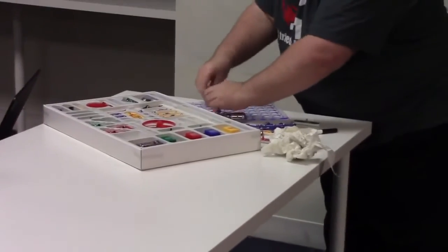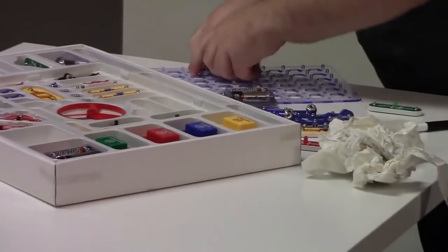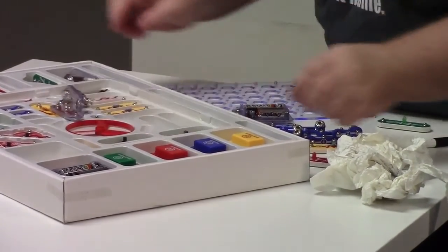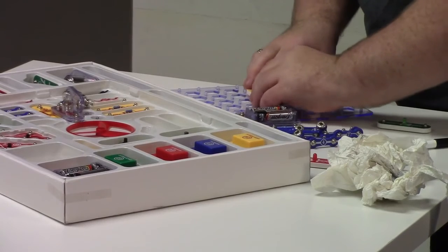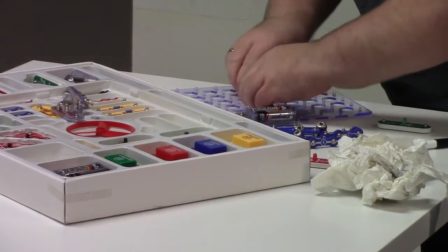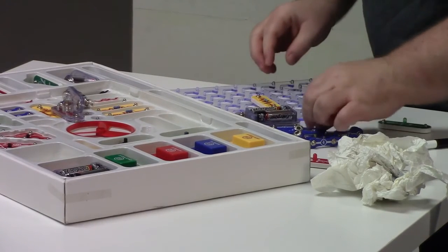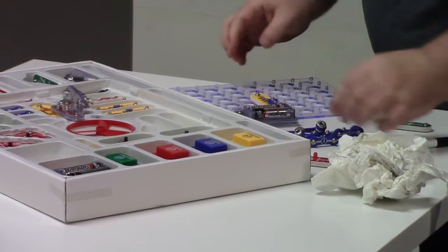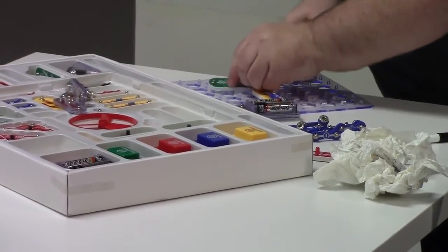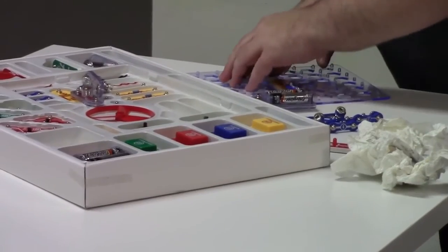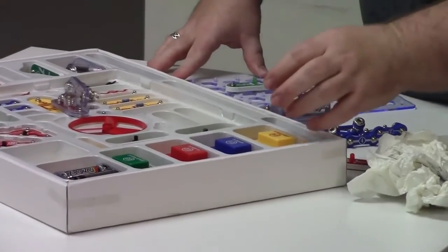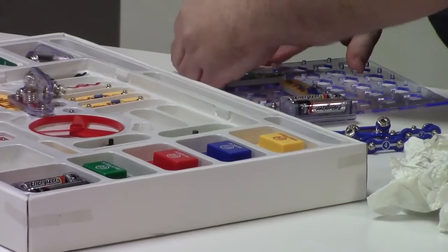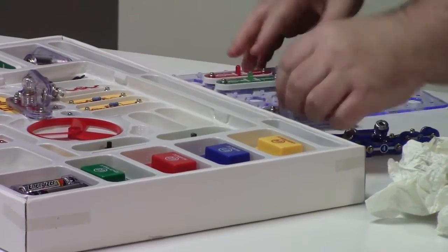Right. I totally started a fire, so I'm like, how did I do that? So as long as there is some resistor on there that's strong enough, as long as you're limiting the current in some way, you will not start a fire. And really you won't start a fire anyway. What it'll actually do, if you actually try it, is flash really brightly for like a third of a second and then never work ever again. It made a lot of really bad smoke, very toxic.